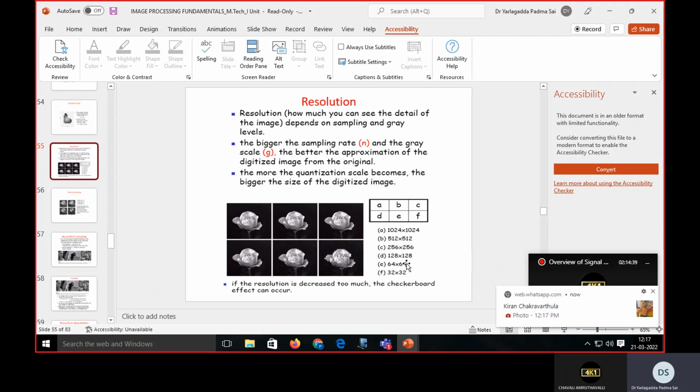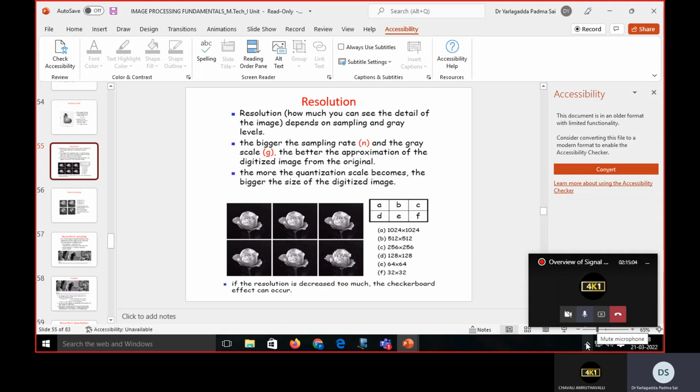They may ask what is the difference between them. In digital communication, the first block is source coding. Once you get your signal, after converting into digital, you do coding, using Huffman coding, Shannon-Fano coding. Like in image processing, you have arithmetic, LZW coding, many coding techniques to reduce at the source level.